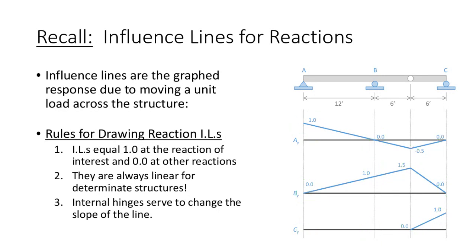And so if the whole point of an influence line is placing a unit load downward, then all the reactions have to equal a unit load upward. That's why when you sum them up, they always equal 1. Okay, that's the first rule.